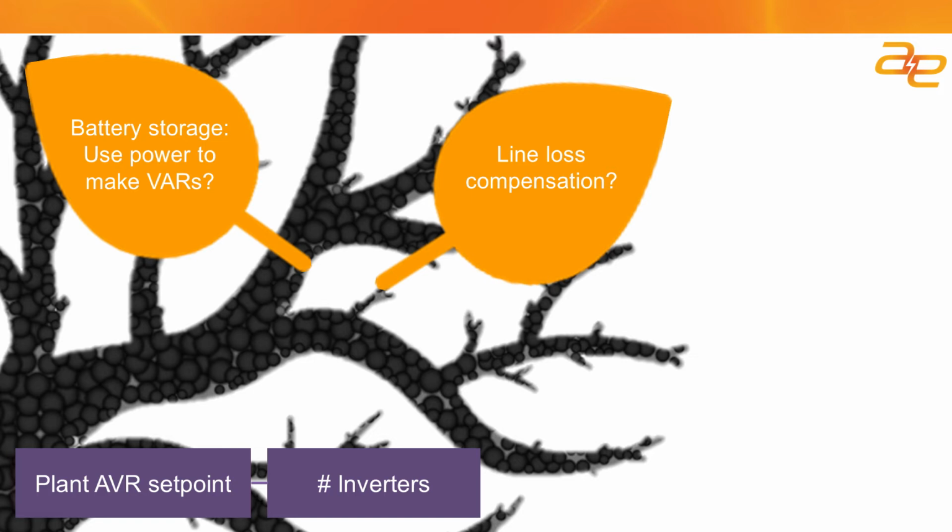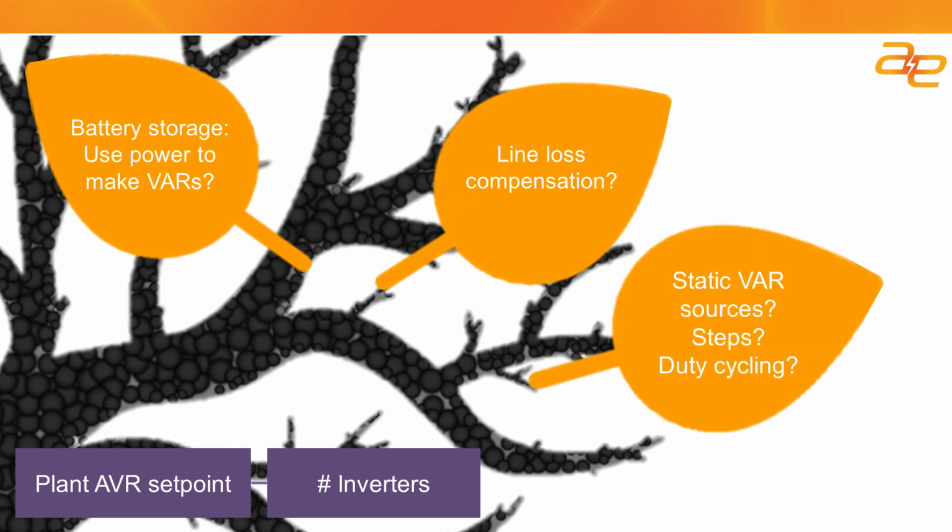So if you're trying to maintain a power factor at that substation, what you're putting out of the site might not be in agreement with what is getting to the end of the feeder line between the site and the substation. So you may need to do some calculations on what the voltage drop is through that line to make sure that you're in compliance with what the interconnection itself is, and not just what's at the point of common coupling leaving the site.